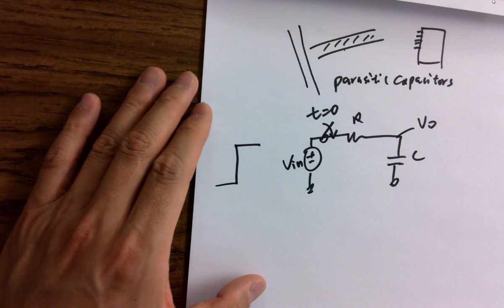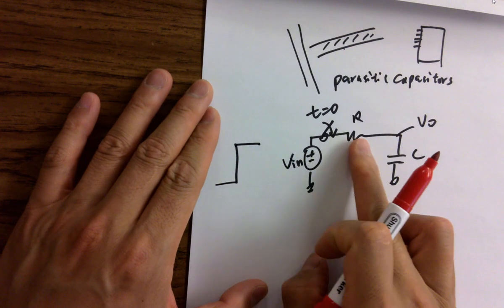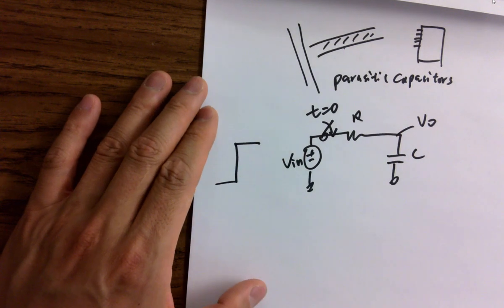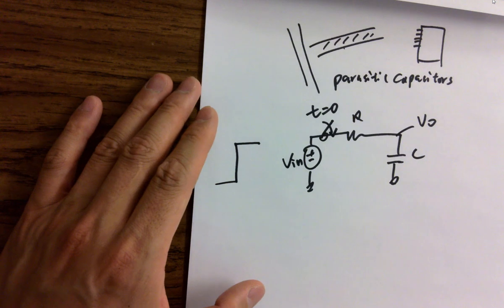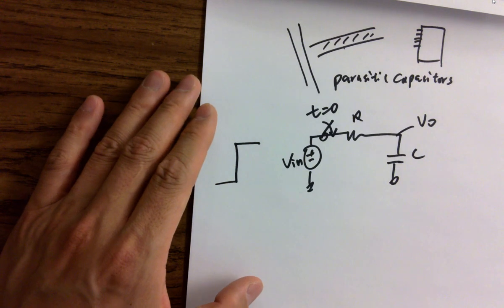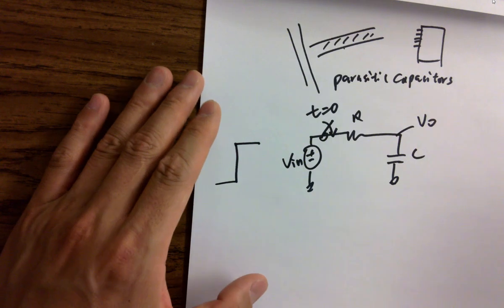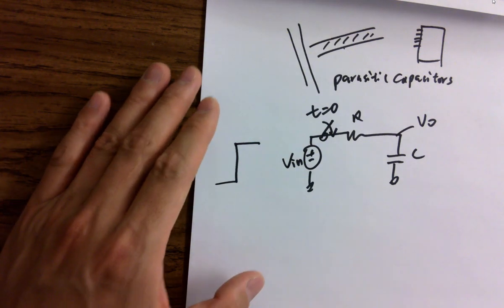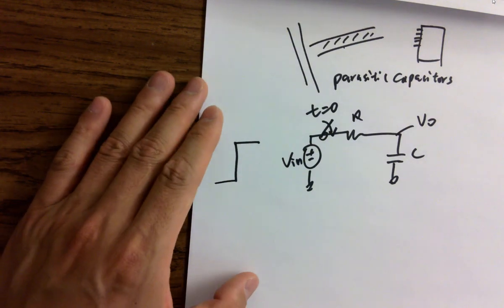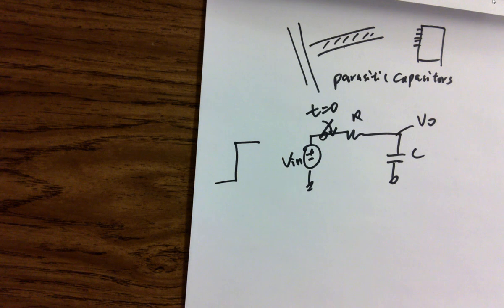However, it takes time. Depending on the size of the resistor and the size of the capacitor, it takes time. That is why it's so complicated in chip design, because you have delays everywhere. You have to do timing analysis. People spend so much time on Cadence because 80% of the time is spent doing timing analysis. You send a clock from the input, and you are expecting a signal 1 millimeter away from the input, right?